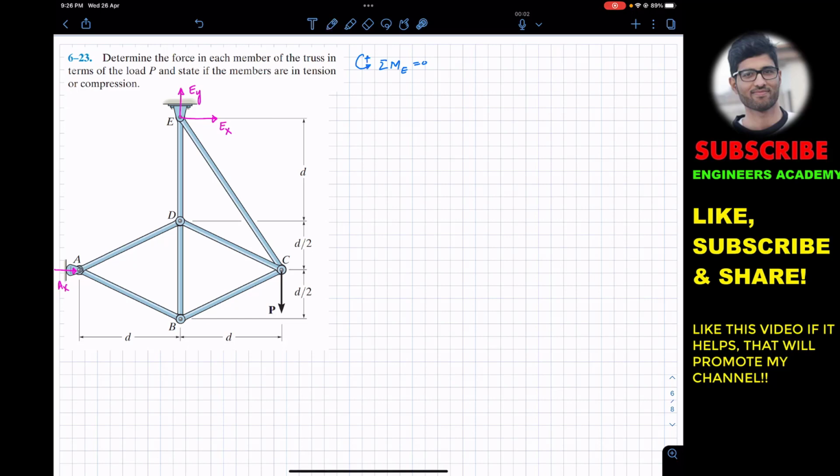Now, if we look into this AX, it's going to produce the counterclockwise moment about point E. So I will write AX, and the perpendicular distance or the moment arm of this AX from that point E is this distance from here to here, which is D plus D divided by 2. This is 3D divided by 2 actually.